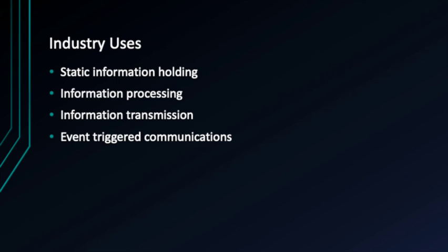A server can then cycle through each client and therefore each room to collect the required information. Once collected, the server can then send control information to the central HVAC system to manipulate each room's dampers and fans accordingly. The system can then be fitted with certain event-triggered communications that override the normal message traffic for events such as fire or poisonous gas.